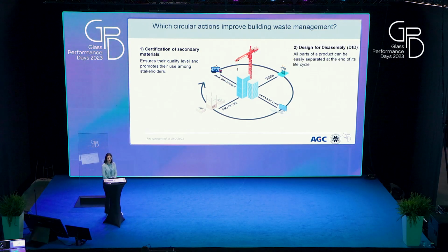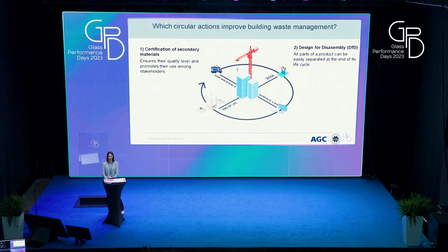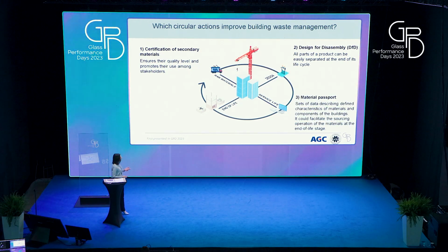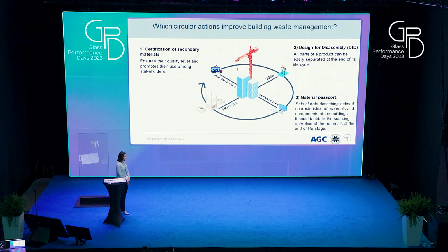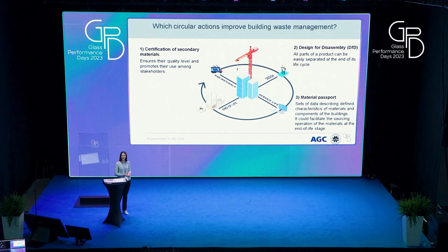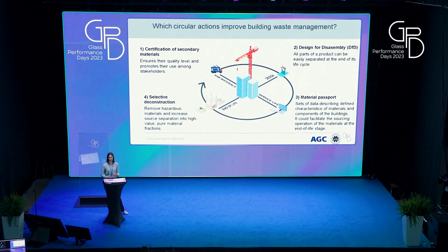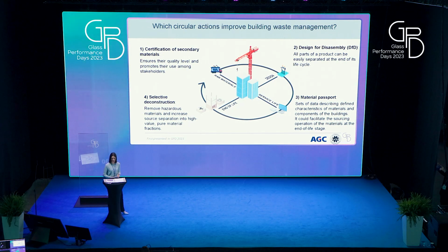Then, during the design phase, we should really try to integrate the design for disassembly approach in order to allow that all the materials and components of the system could be easily separated in the end-of-life stage. Then, during the service life, having the metadata of a material or of a component is really useful during the collection and sorting operations that could happen at the end-of-life stage. And in the end, selective deconstruction is preferred over demolition, because only in this way could we collect, separate and recover the materials of the buildings.